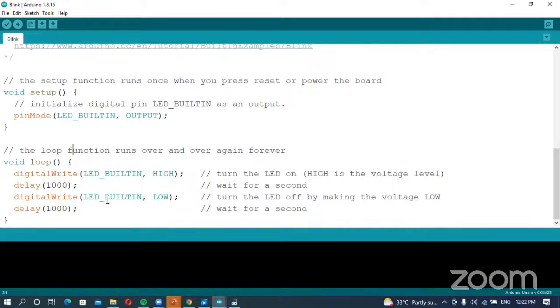Here we initialize the variables for that C program. But on the hardware side, in embedded systems, we initialize which pin we want to use in future. We need to describe your pin, whether it is input or output. Actually, pinMode is the keyword.